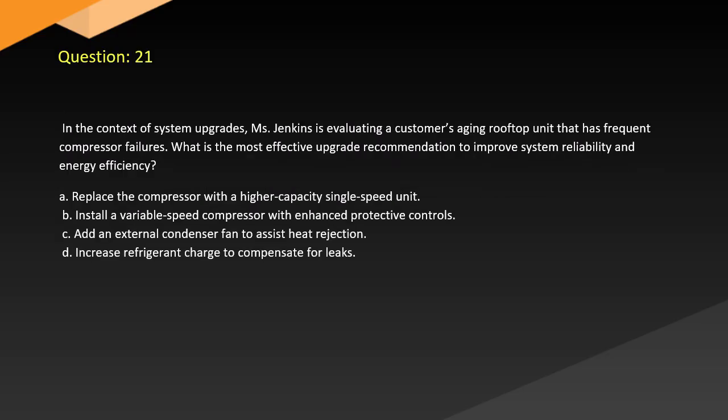Question 21. In the context of system upgrades, Mr. Jenkins is evaluating a customer's aging rooftop unit that has frequent compressor failures. What is the most effective upgrade recommendation to improve system reliability and energy efficiency? A. Replace the compressor with a high-capacity single-speed unit. B. Install a variable speed compressor with enhanced protective controls. C. Add an external condenser fan to assist heat rejection. D. Increase refrigerant charge to compensate for leaks.